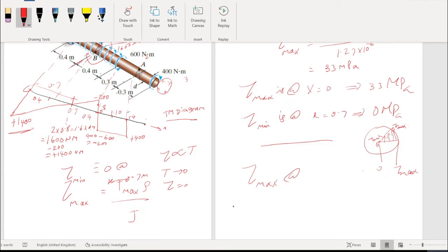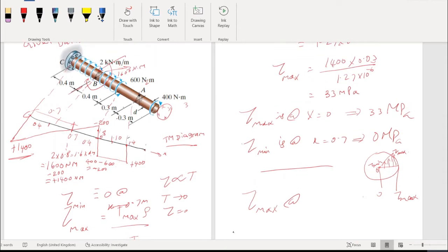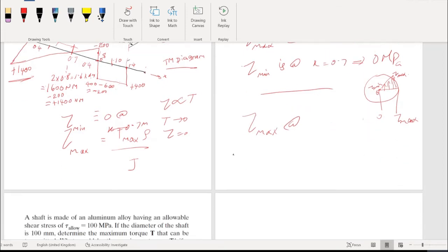Hence, the distance from the center to the wall is important to know how the layers from this point to this point, from center to the wall, are shearing one over another due to rotation. You really have to imagine how this is. Imagine perpendicular to this circle, it is being rotated, being fixed at C or at the bottom. So the layer one over another gets twisted or sheared about the longitudinal axis perpendicular to this circle. Okay.